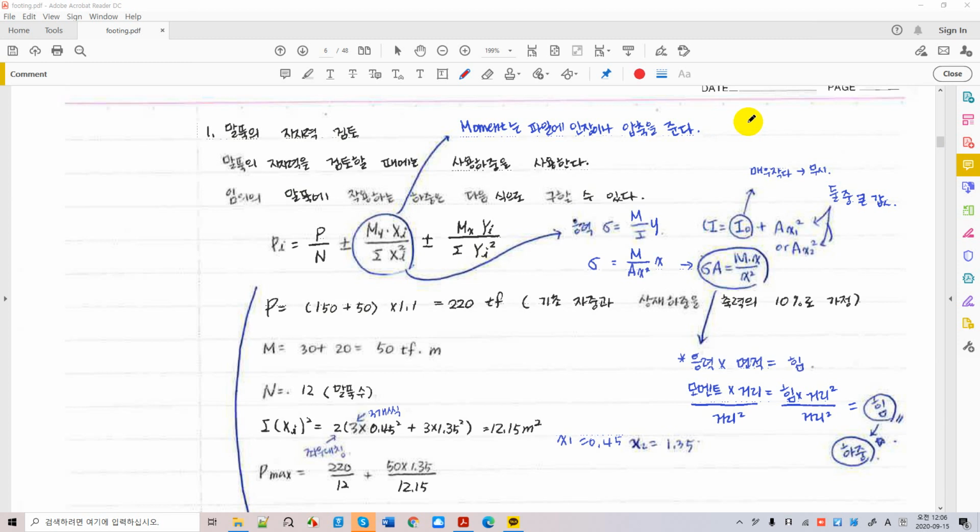So, for example, if your axis of moment of inertia is here and your column is over there, then you have to calculate the moment of inertia of the column itself, I0, right there. Then you have to move this to the axis of moment of inertia, defined by x, for example. Then you have to consider extra terms, in which you calculate A times x squared, right? Okay, so this is all you have.